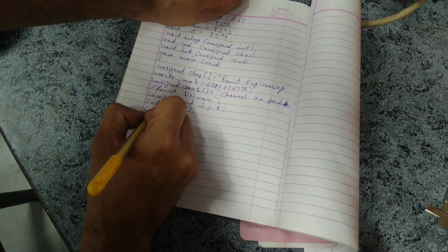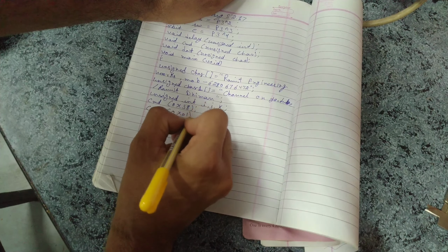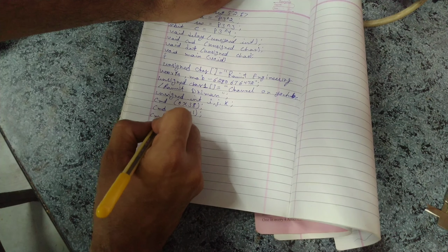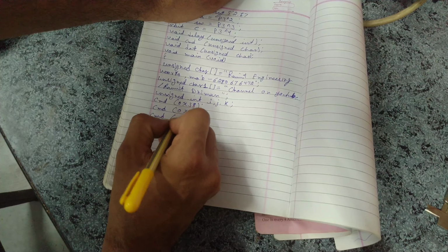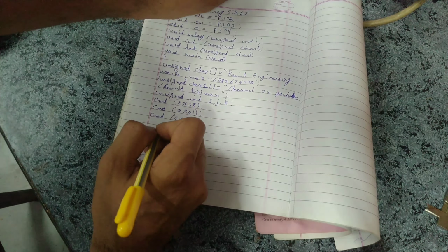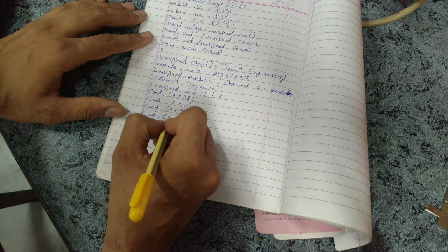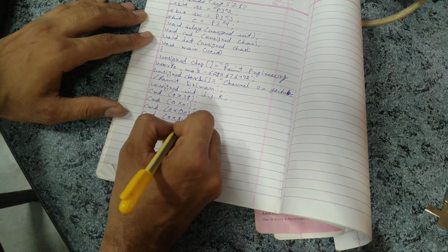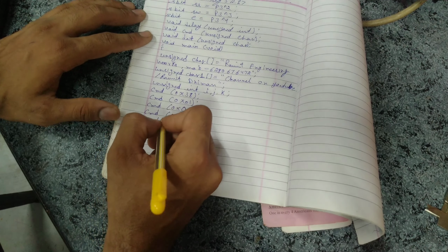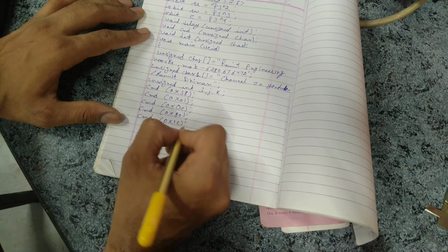and again command, we used the first line skipping, which is the first row, first alphabet, and then starting the second one with the command which has to enable the LCD, which is 0x0E. It's the third line, and again we use the command 0x80. Here you can use the LCD table from the data sheet so that you can confirm that the values are the same as present in the data sheet.